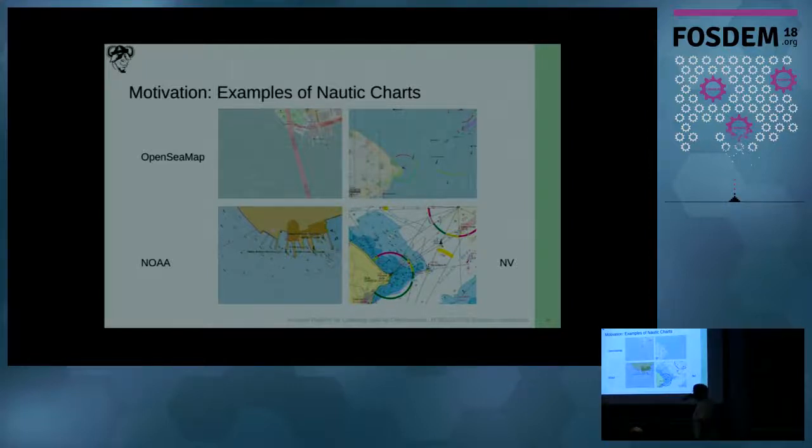And a little bit better it is here in the Kiel area. So we have the lighthouse of Kiel on the top right corner, and another one here. And the most important areas where the big traffic goes is this one, so it's also marked. That's quite interesting. This is a current updated chart from a real provider of these charts, and it has much more details, especially these very detailed depth information. If I have a vessel that needs 2 meters of depth, then I shouldn't go in there, because here is a 1.1 meter mark and I will get stuck on sand and probably not go on anymore.